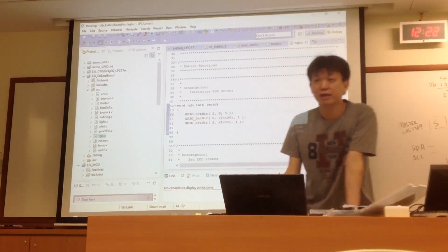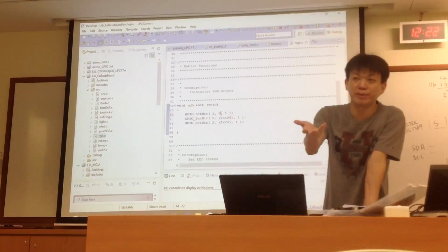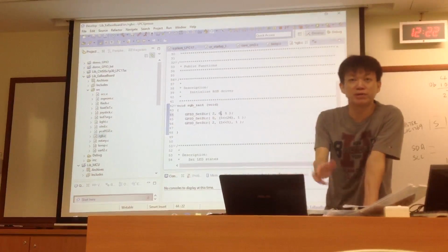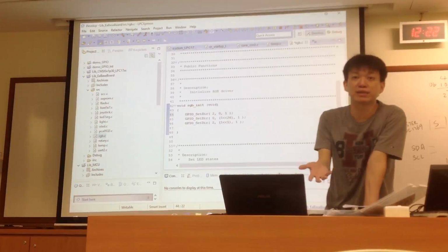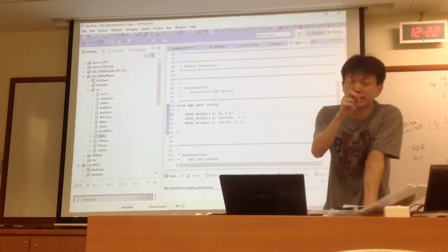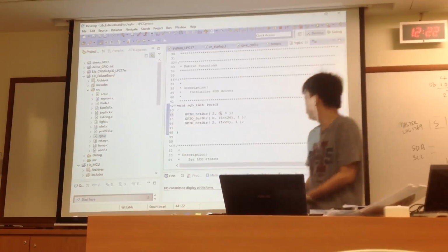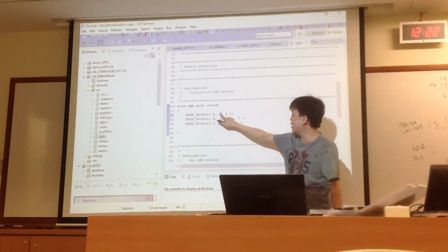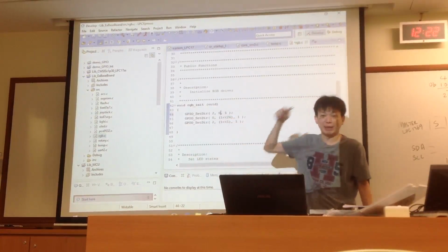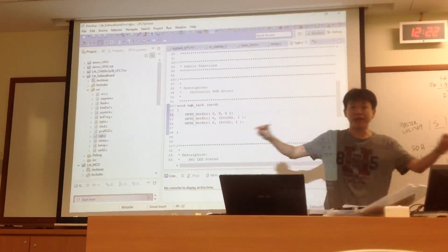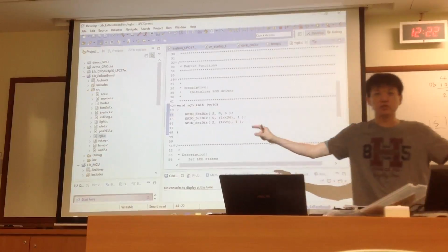I think you remember this from this week's tutorial, right? If you put 0, they won't do anything. They only recognize and update the bit with 1. The pin which is given as 1, they will update it to 1 for that particular bit. So if you put 0, they will simply remain unchanged for all the 32-bit data.